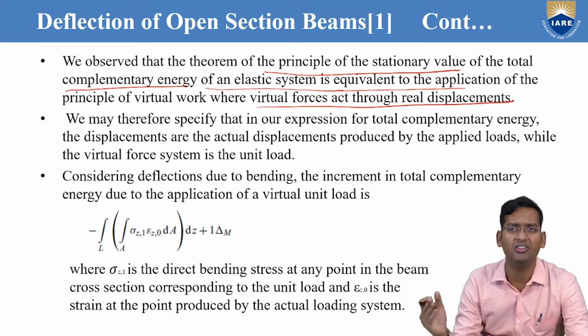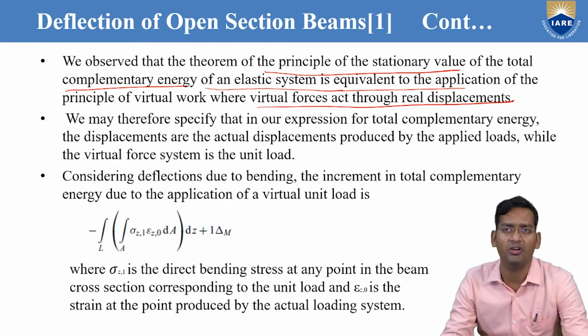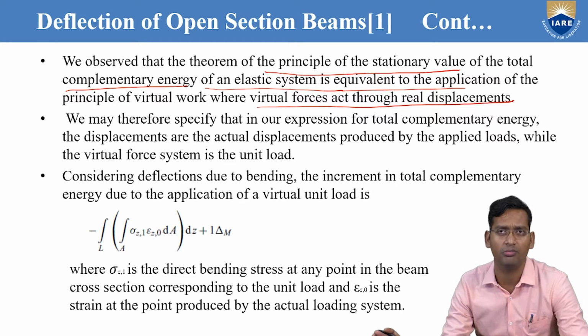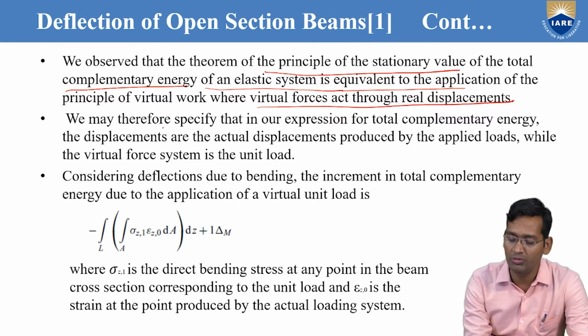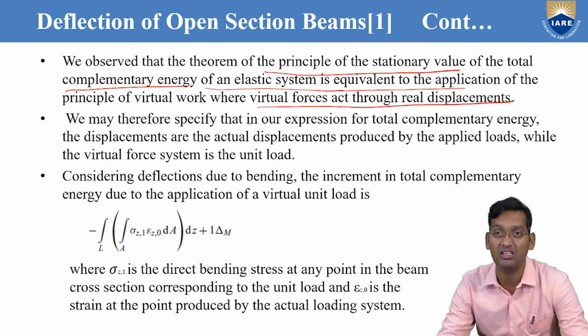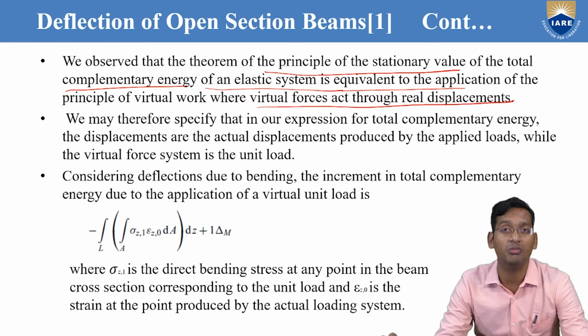And same thing later we can just remove, because it's a virtual force. So after getting that one, we can remove the virtual forces later. So we may therefore specify that in our expression for total complementary energy, the displacements are the actual displacements produced by the applied load, while the virtual force system is the unit load.